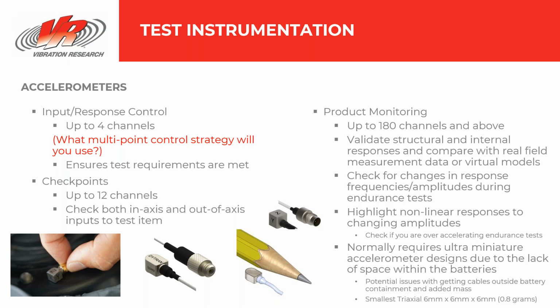So this really is an issue associated with accelerated endurance tests where you're time compressing your endurance tests. If you're starting to get changes in response at the endurance test level, then you might need to rethink the actual test levels you're applying, as you may get non-realistic failures because of it.